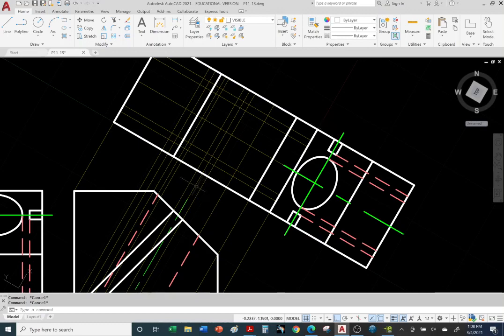Okay, so this line is the one that lines up with our green center line, right? So let's go ahead and draw our center lines first. Okay, get those out of the way, and it will also help us center the hole. Always go slightly beyond. Right click enter, and we can go ahead and shorten it. This is where I need to turn off Object Snap temporarily, but keep ortho on. There it is. Hit escape to deselect. There's our center line. And let's draw this one here.